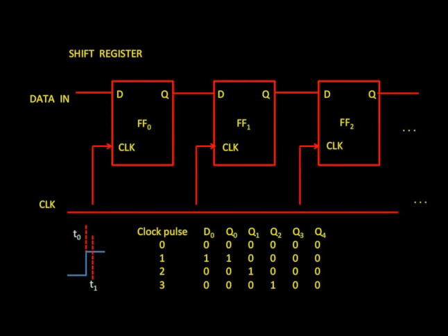The effect is to take the Q values in the row in the table immediately above and shift everything one column to the right. The pattern continues with each new clock pulse. A new data level comes in at the left, and one bit at a time, everything else shifts to the right. At the far right end, the data can be shifted into a computer interface or other device. The shift register plays an important role in reading out data from cameras and diode arrays and instrumentation.